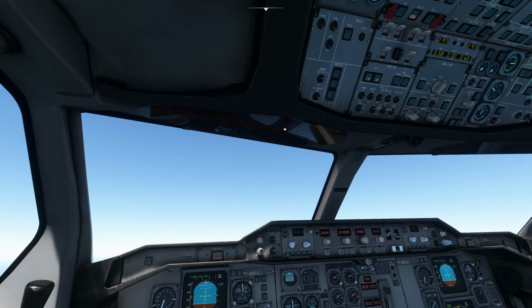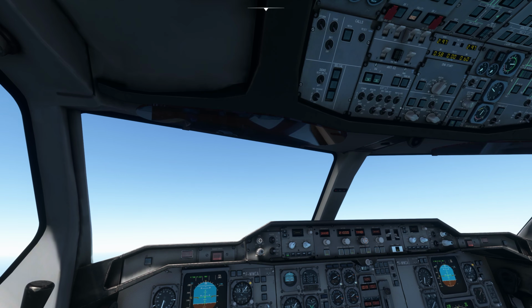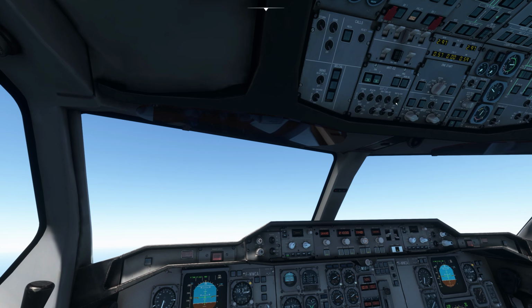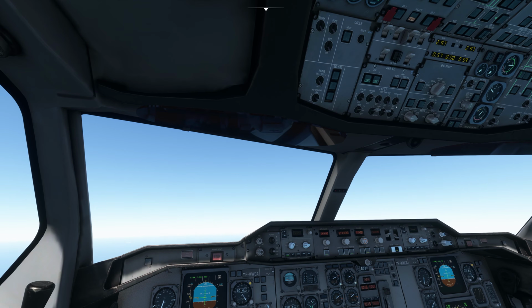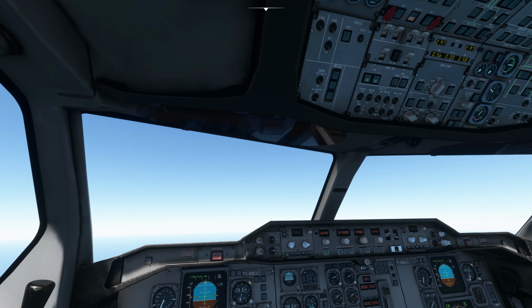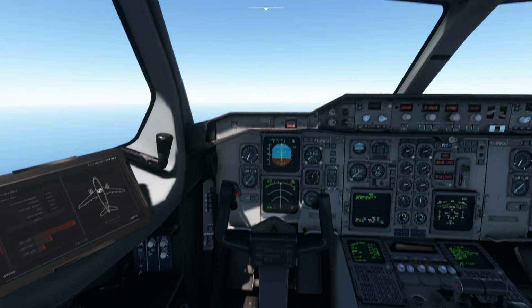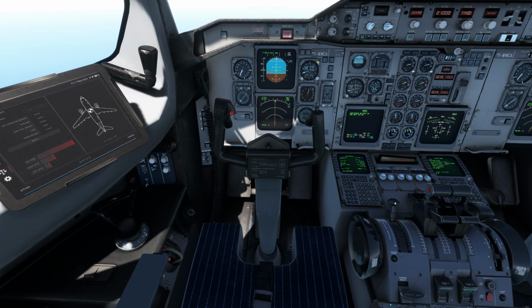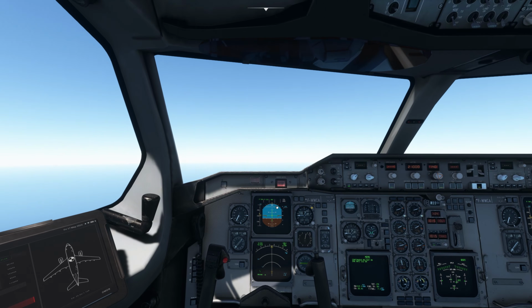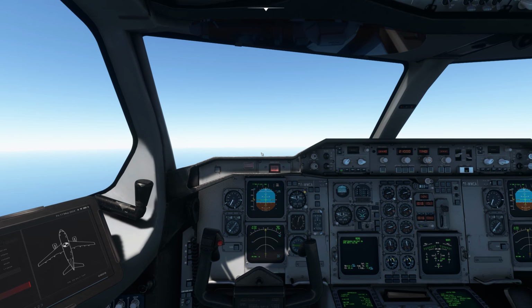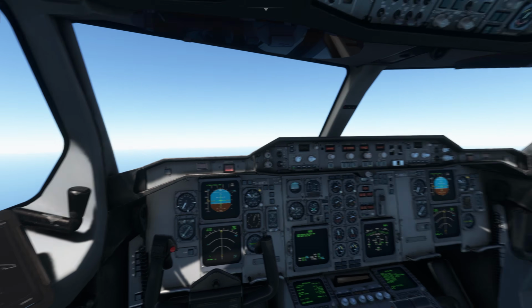Now, as the plane is crossing 10,000 feet, I can turn off the seatbelt signs and I can turn off the lights. I'll set nav to only nav. Logo will be off, but nav lights will be on. Wing light off, and the landing lights also off, and the taxi lights also off. Now you have turned off these lights, and you can also disarm the speed brakes. That's it. Now the plane is climbing to 21,000 feet.